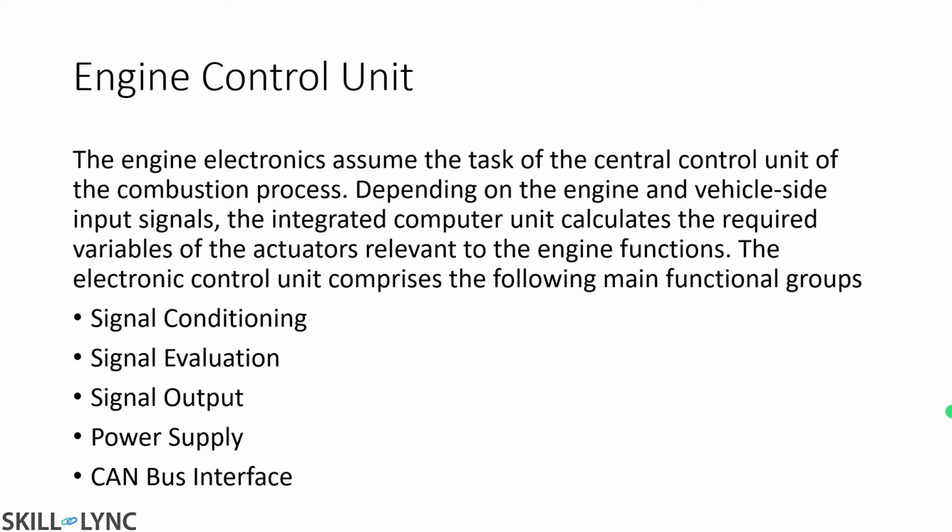All the three sensors are going to give us pretty much the same value. Let's say one of the sensors throws out a value of 90 and the other two sensors throw out a value of 120. This is going to tell the ECU that something is wrong. Two values match, but the third value doesn't match with the other two, or it's not in a plus or minus 5 range. So the ECU is not going to know exactly where it's wrong. It could just be a sensor fault, or it could be that something has terribly gone wrong.